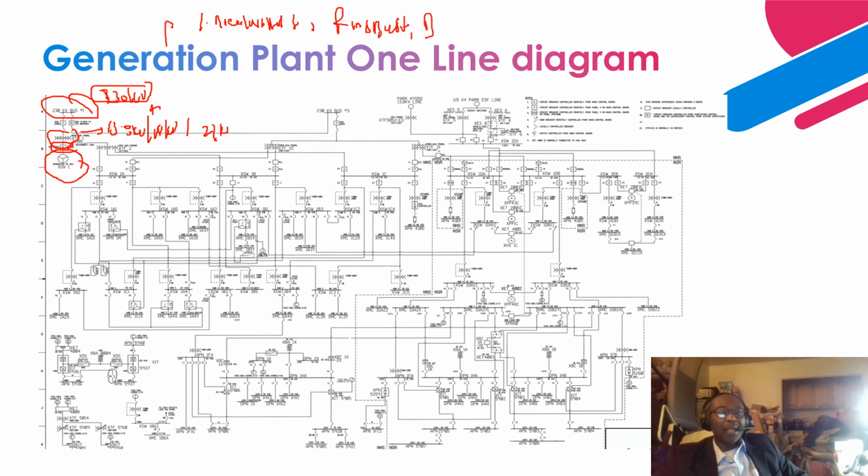You have a double bus and double breaker, right? For that voltage level, these are the type of bus schemes that are applicable at that voltage level, right? Because the single bus scheme is applicable to a medium voltage level, and the double bus with a double breaker with a sectionalizer is applicable to the medium voltage level.